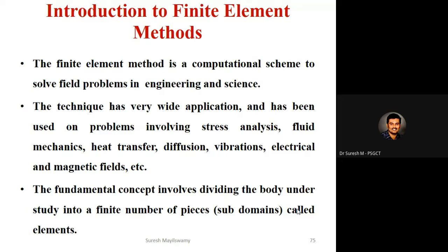The fundamental concept involves dividing the body under study into a finite number of pieces called elements. Particular assumptions are then made on the variations of unknown dependent variables across the element using so-called interpolation or approximation functions. This approximated variation is quantified in terms of solution values at special element locations called nodes.